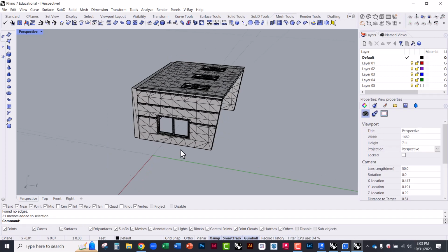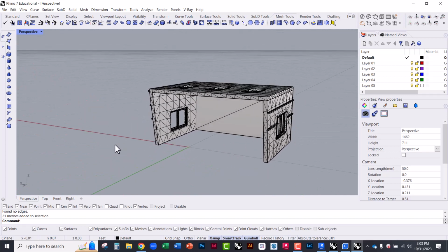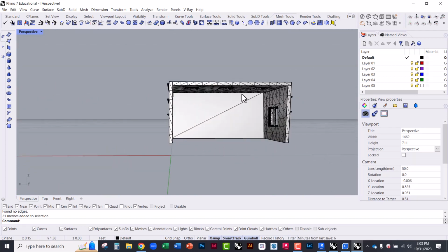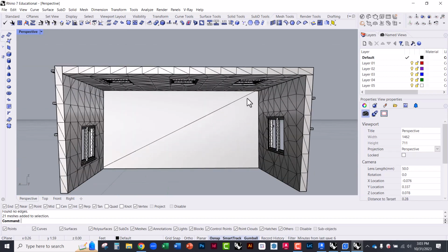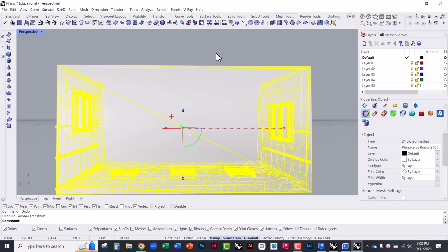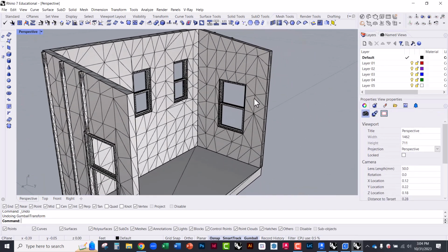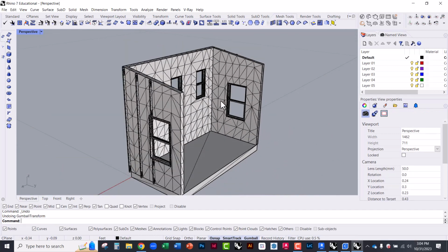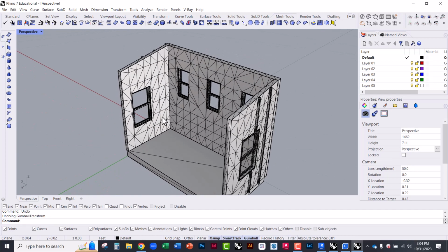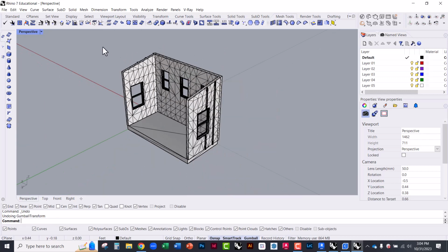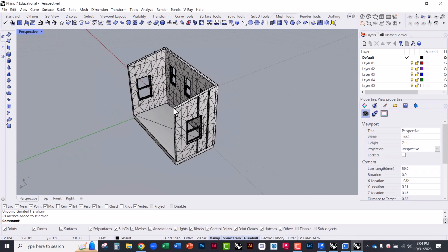If it were oriented this way, it would require supports, right? It would have to support this entire wall. So the orientation that we print matters. So just being smart about reducing the amount of support material that it's going to need can save you a ton of time and material waste. When you consider this is often ABS or PLA plastic, just reduce the amount of plastic waste that's out there.